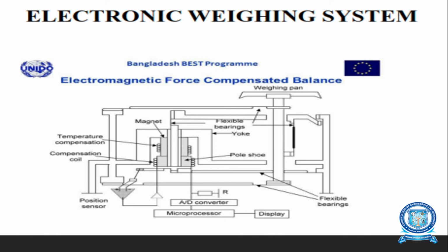The signal from the load cells is added and amplified to give an output of 0 volt to 5 volt or 4 to 20 milliampere for process instrumentation. It is further converted into a digital format with an analog to digital converter so that the output can be indicated or printed out in a digital format or used for processing. The electronic weighing system can be designed to integrate with a computer system with suitable software to include all functions such as totalizing, averaging, counting, and processing or any other such control operation.